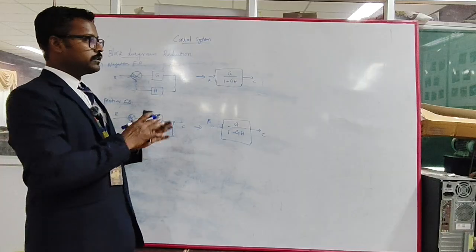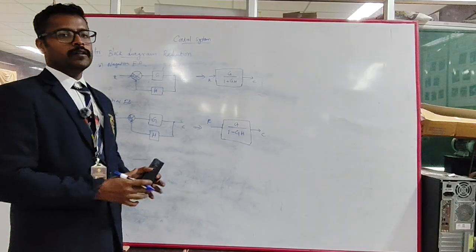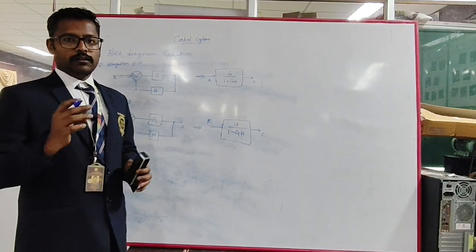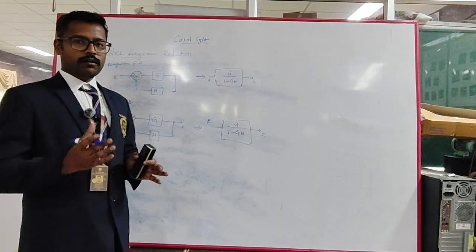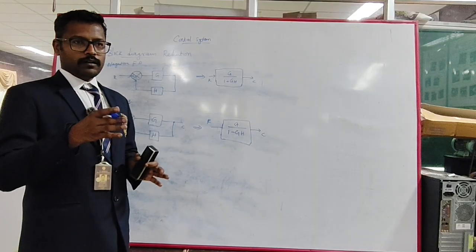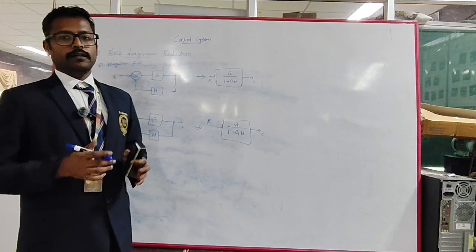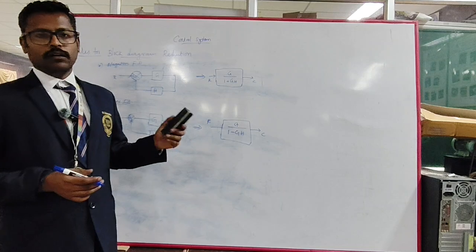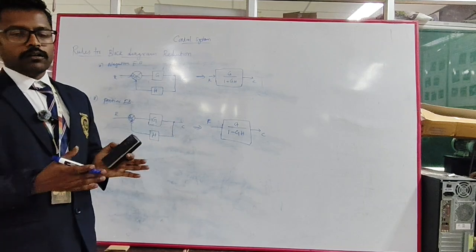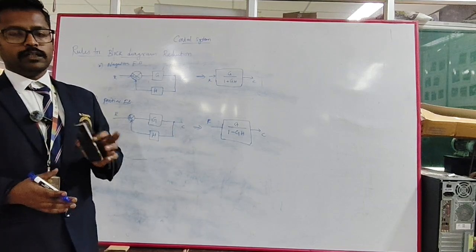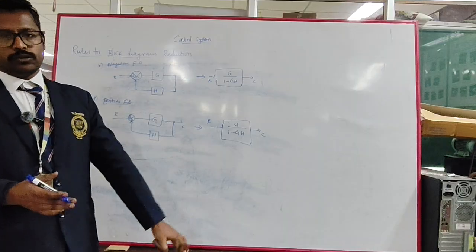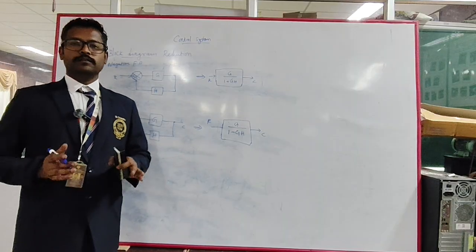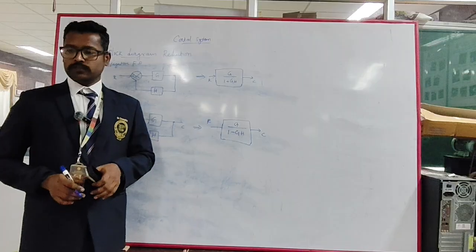The system is represented with the help of a huge block diagram, but we need a single transfer function which will behave like the original system. So in such conditions we use block diagram reduction, which will give you the single transfer function, and which can also be used to deploy controllers onto those systems.